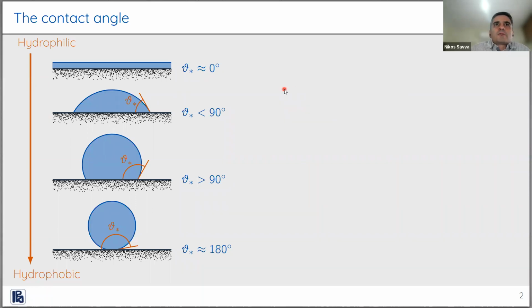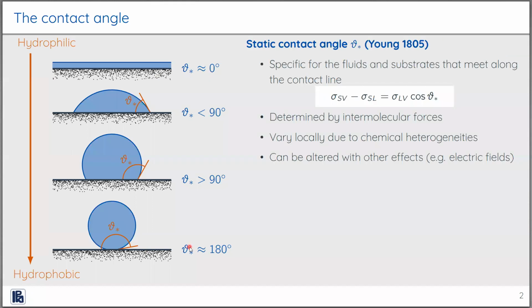So as the contact angle increases from 0 degrees, the fully wetting regime, which can occur, for example, if we have silicone oil on a glass plate, all the way to 180 degrees, where we have the non-wetting regime, there's a breadth of angles going from hydrophilic to hydrophobic angles. So this angle has been known since the 1800s.